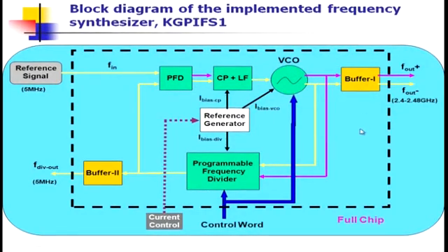Then another thing you have introduced is that I want to test my loop in closed loop or open loop. Therefore, for the free running frequency, I want to check only the VCO frequency. I am not interested in the divider alone. So, what we have done, look at this pink line. That yellow line and the pink line, the differential one, goes to a buffer, then is finally fed to the output. That is the output pin, with a ground in between, a source-ground-signal SGS kind of arrangement, so that you can get the differential output or the signal.